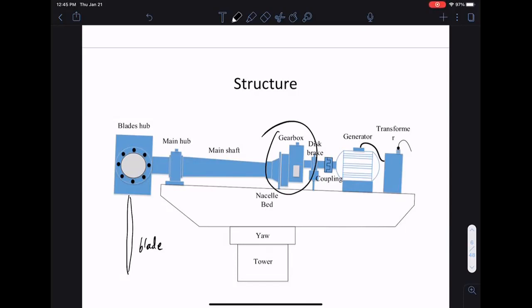And as we go through the class, we'll see how we replace this gearbox. Okay, so we'll cover basically 4 types of turbines. You can think of the 4 types as, by type 4, the idea is let's get rid of this gearbox. Gearboxes are the things that cause problems. So that's one thing to keep in mind: the gearbox. When people say these things require a lot of maintenance, a lot of times this maintenance just happens in this gearbox. Any questions about this?